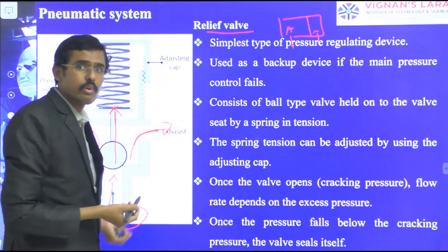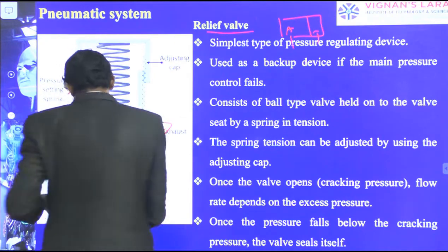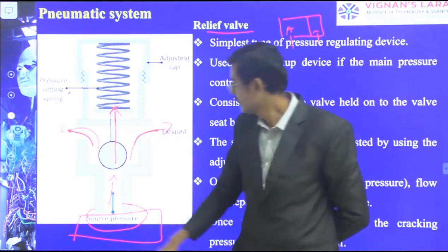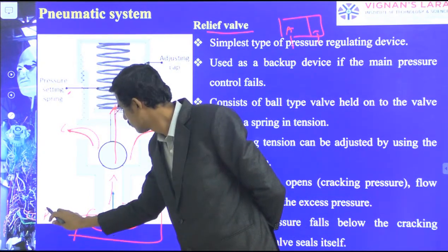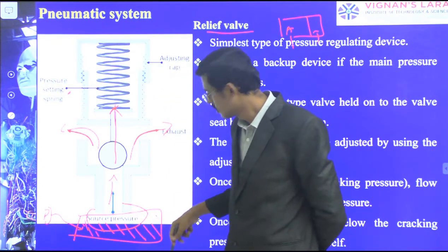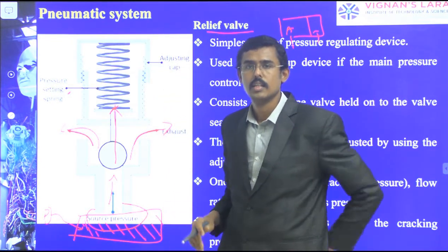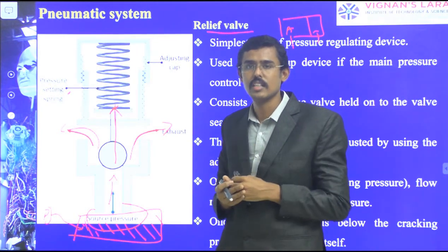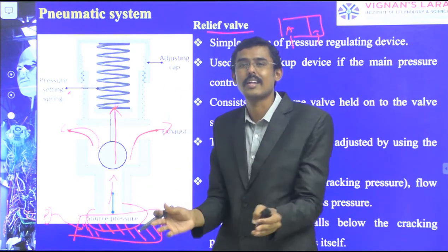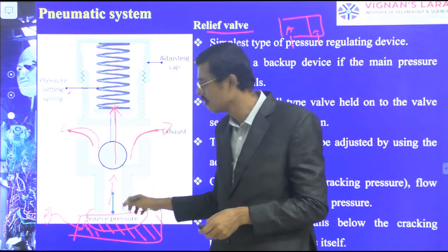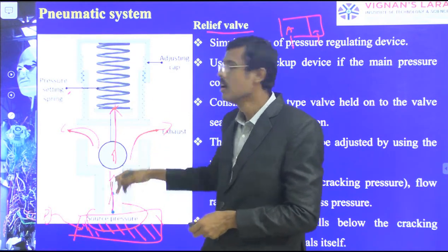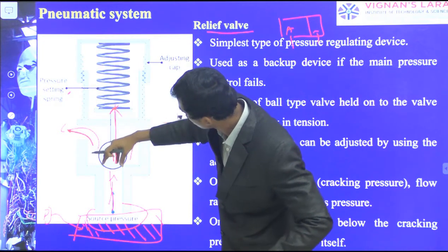Why am I naming this a relief valve? Here, let us consider a compressor. We have the filter, and then the air is stored here; the compressor keeps on filling. Air is filled now. Air is exceeding the limit of the reservoir tank. There we have the relief valve in such a way that only high pressure can push this spring return. Otherwise the spring return is going to keep the force on here.